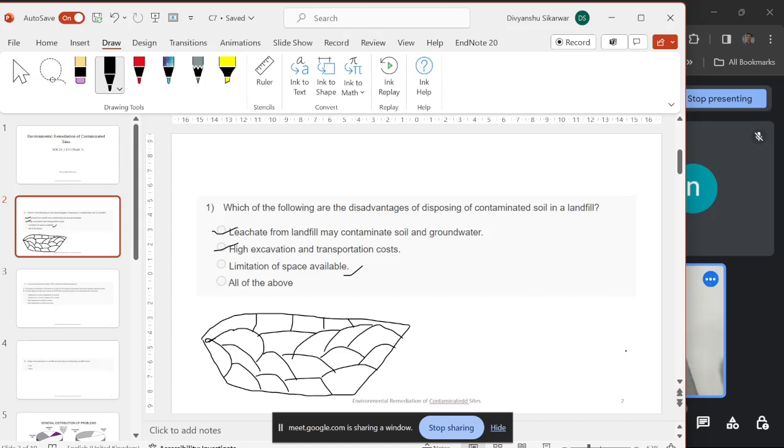For that we use different things. If we consider solid waste, we will try to extract organic matter. We will try to extract energy, or convert it into fertilizer using different methods like anaerobic digester, and we'll prepare compost and all those things, right? For inorganic waste like paper waste, if the calorific value of the waste is high, we will try to burn it in an incinerator and extract some energy. At the end, we will try to minimize the waste going to landfill, so that the landfill stays for a longer period of time, right?